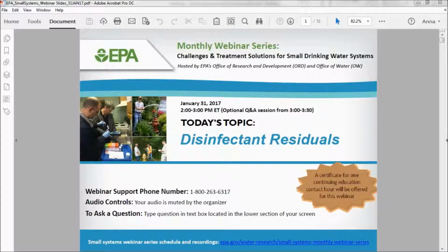Okay, thanks, Dave. Here's a question. I think I'll throw it to Matt, but perhaps others can answer it. If I sample at a site that has a free chlorine residual of 0.5, but my pH is 11+, should I be concerned? So this fits as a segue into that question.